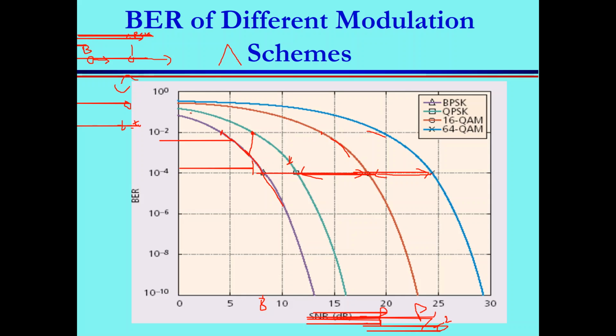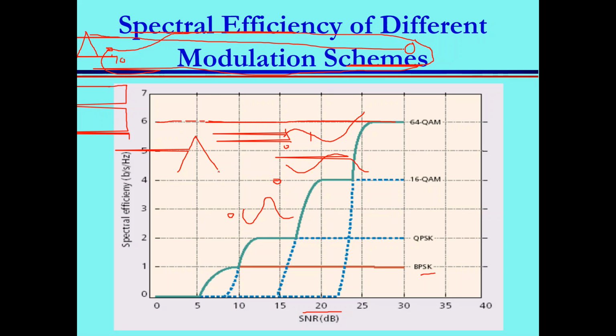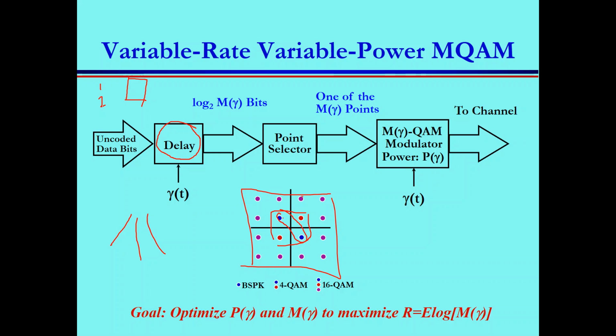Clear? Yes, one question. If somebody reaches a point between the two curves, between QPSK and the next one, what's the modulation regime? Here, exactly, yes. In this case, this is rough tuning. We have fine tuning. You can achieve fine tuning by integrating coding with modulation. When you integrate coding with modulation, you get very small step size between them. So you always have one curve very close to you. But now this is rough, which is something we call adaptive coding and modulation. So you got the idea. This is the most important thing.